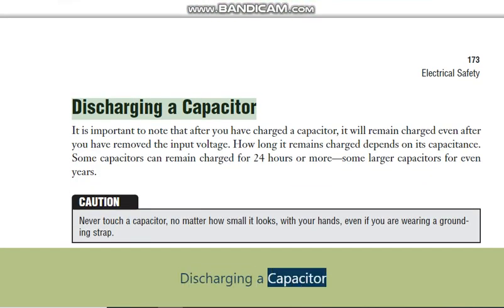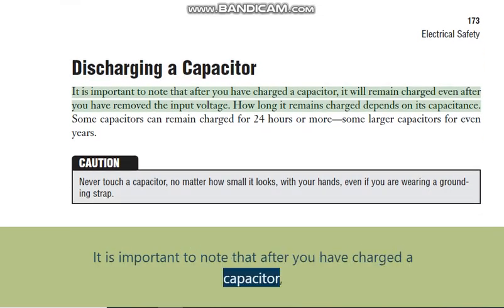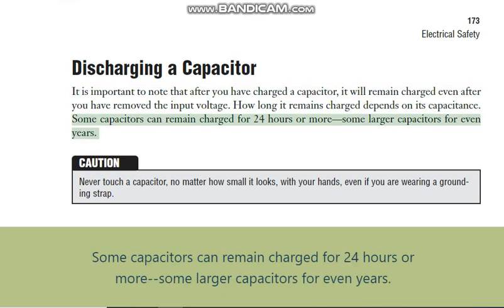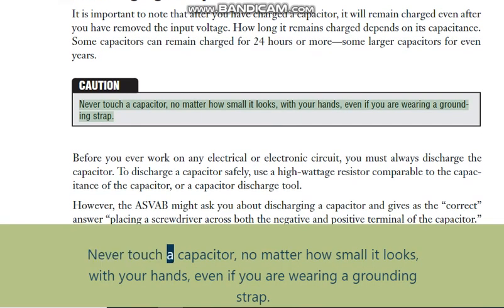Discharging a capacitor. It is important to note that after you have charged a capacitor, it will remain charged even after you have removed the input voltage. How long it remains charged depends on its capacitance. Some capacitors can remain charged for 24 hours or more, some larger capacitors for even years. Never touch a capacitor, no matter how small it looks, with your hands, even if you are wearing a grounding strap.